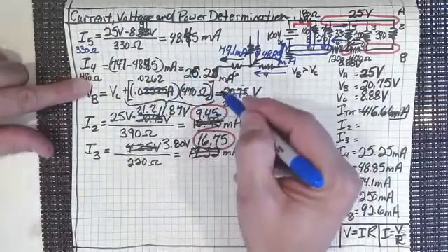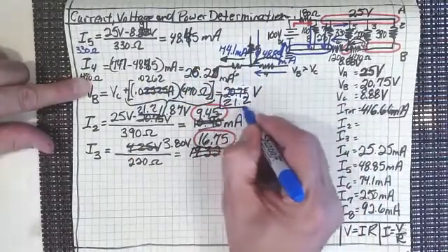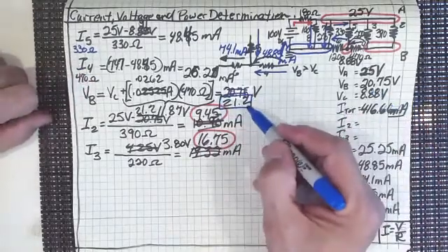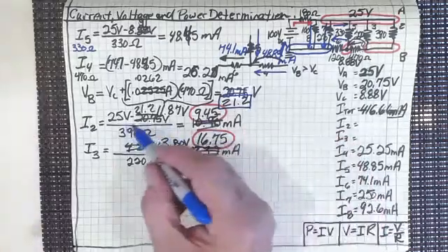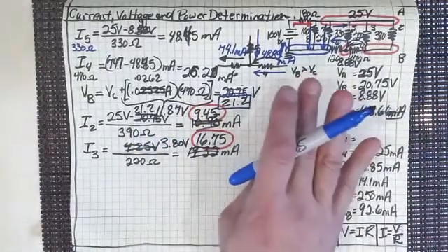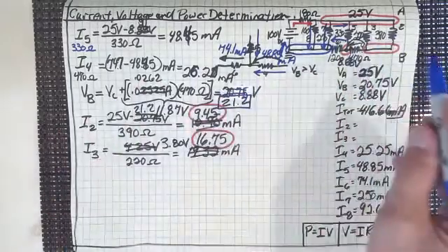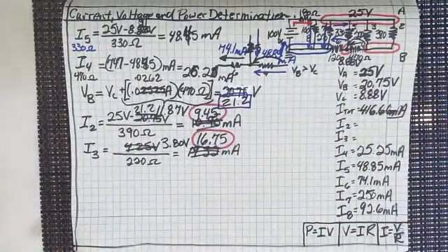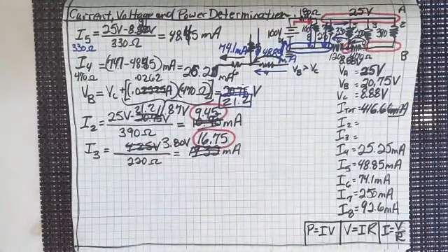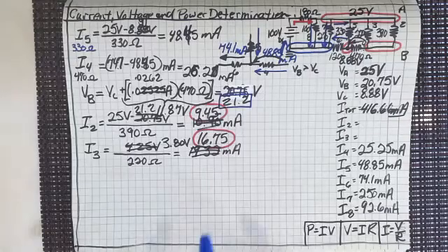I placed that back in here, and I found out that our voltage there actually isn't 20.75, it's 21.2. And, working all of that out, I only found that I had lost like 5 milliamps in all of the analysis we had done. I thought, well, that's significant. But in fact, it was just propagation of calculator error, because instead of using 5 significant digits, I only used 4 significant digits at most places.